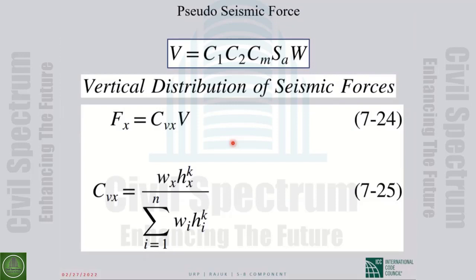So you saw software analyzes the buildings, and then you introduce load combination, and due to the superposition, software combine the results. But of course, in nonlinear analysis, that's not true.